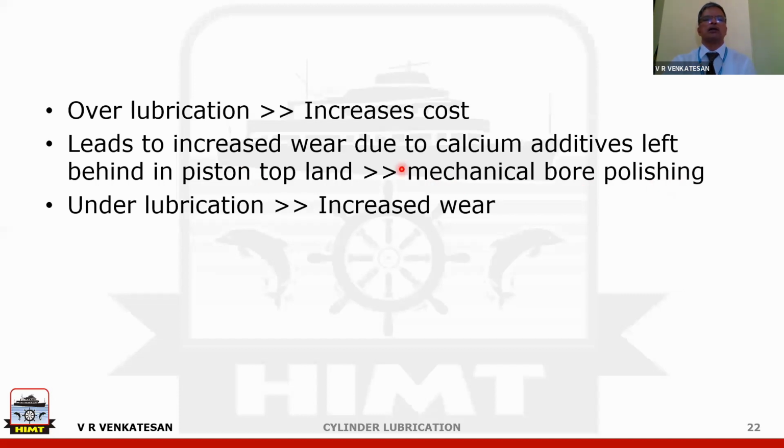So what has happened in many vessels is that if you lubricate too much, you actually spend more money. In addition, you also cost more wear. So it is very critical and important to control the quantity of lube oil that is used. In the same way, if you have under lubrication, then definitely increased wear will be there, because if you don't give enough lube oil, severe scuffing will take place.